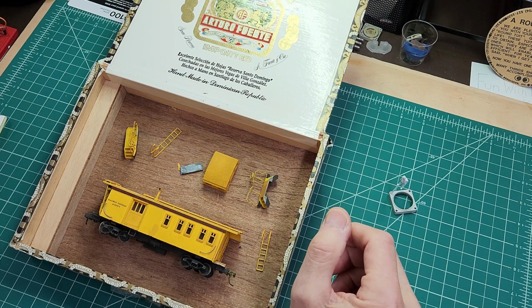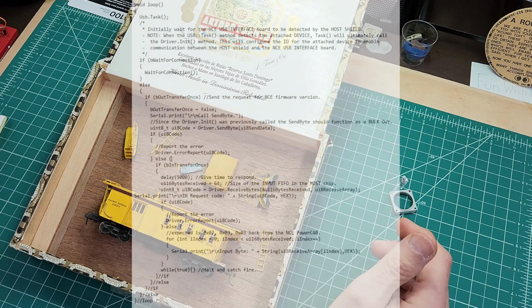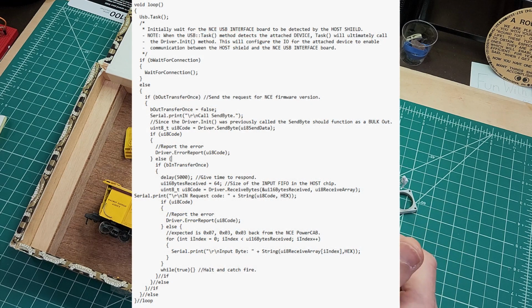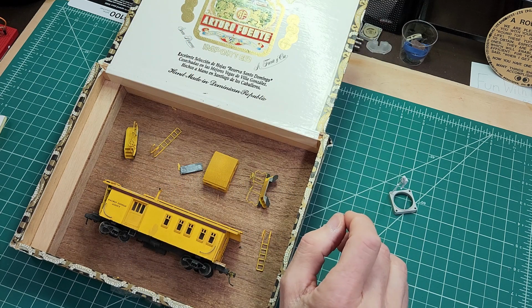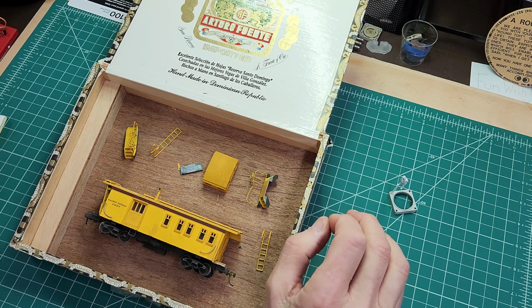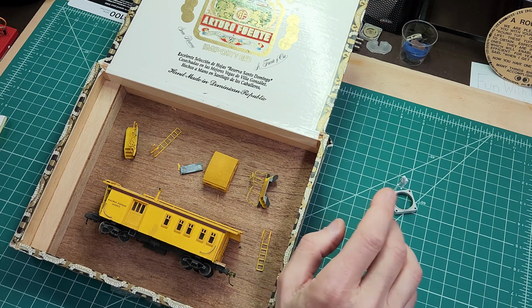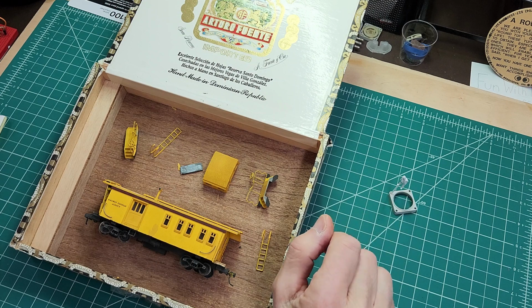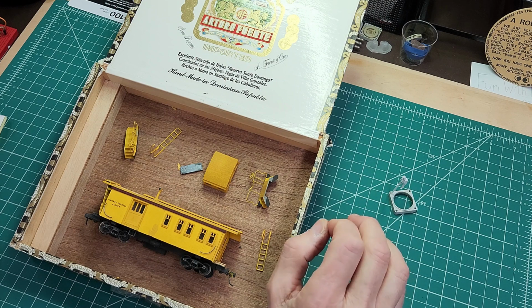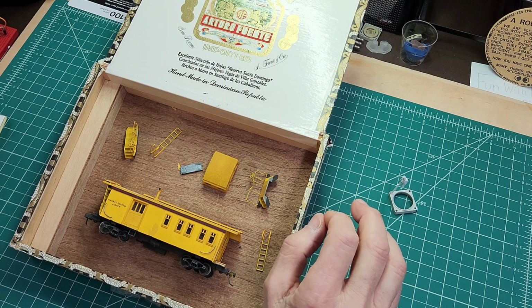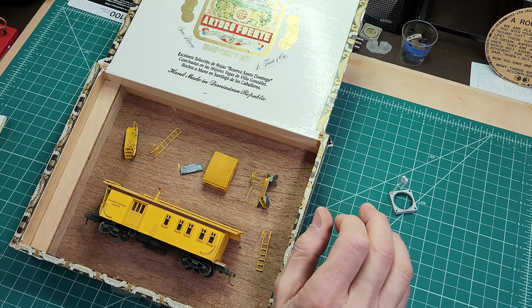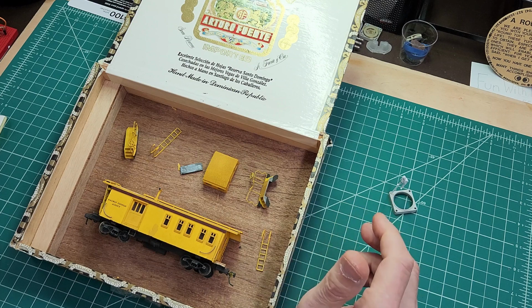I'm showing next my loop code here. Every time the loop is executed, it calls the library's task method here. The task repeatedly checks for an attached device as the first step of a state machine. Detection depends on the Maxim 3421E USB controller chip's internal hardware, so correctly having the chip's 3.3 volt supply is essential.